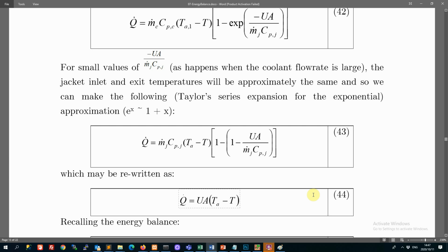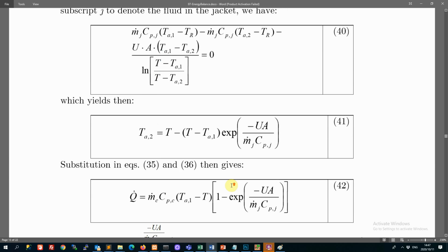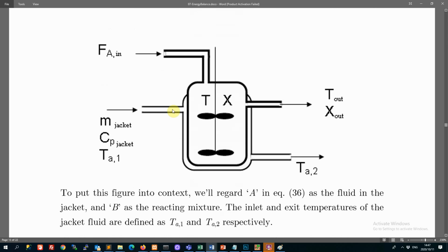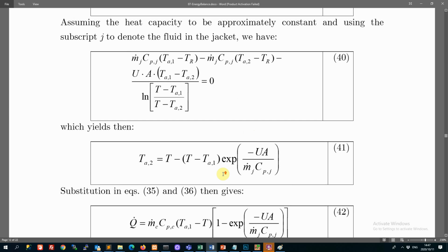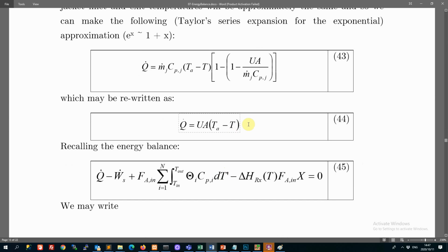Right, and you see it's really wonderfully simple now. You just need one value, and normally we'll just go and say, just use that temperature there. And we know this reactor is running at one temperature T, it's trying to be perfectly mixed. So you just need one temperature difference here, and you do need an overall heat transfer coefficient. We at least have to do that much. And you just need the inside area of this wall, or the effective area across the thickness of the wall, if you want to be more precise. So anyway, for your CSTR, you can make the case that it's as easy as that.